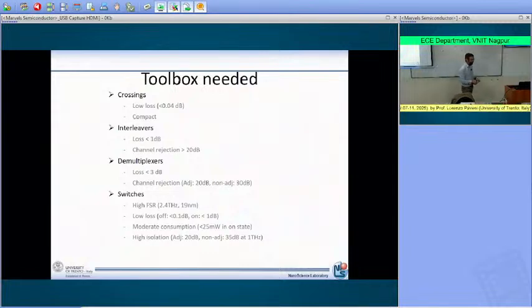And in order to avoid this, I need to have a free spectral range that is larger than the overall span of my lambdas. Meaning that I want to have a free spectral range that is something like that. Okay? In this way, I'm sure that when I'm moving this resonance here, I'm not affecting lambda 12. Okay? And this is the reason why I want the free spectral range to be large enough in order to accommodate all the different lambdas.